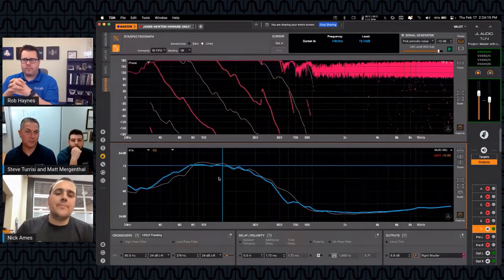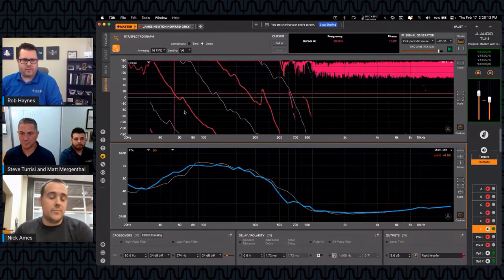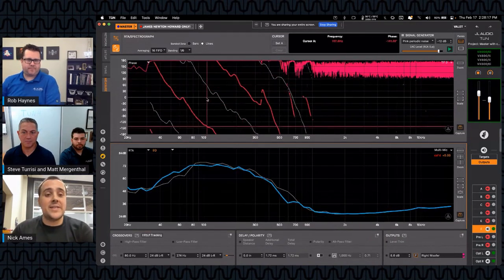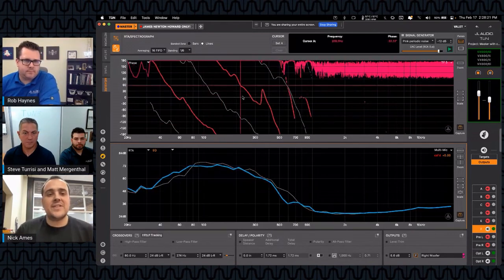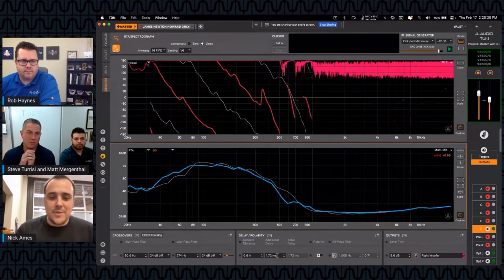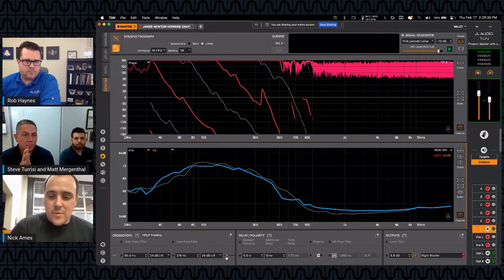That's right. So I unmuted this other mid-bass speaker, and I see, well, it's out of polarity. So up here in the phase graph, I can see that it's in the same time, and you can tell it's coming in at the same time because of the angle of the phase slope. So for example, this says 1.72. If I take this back to 0,